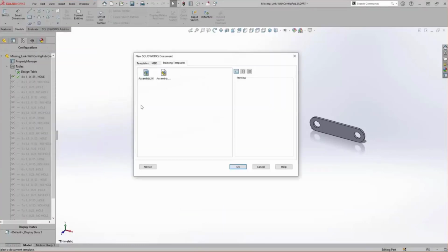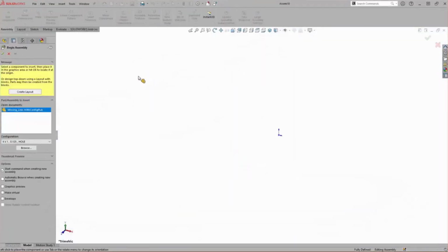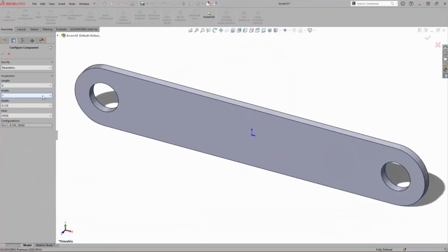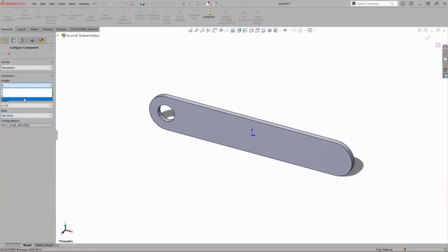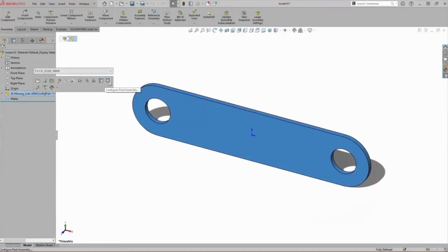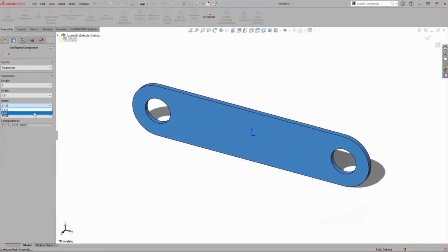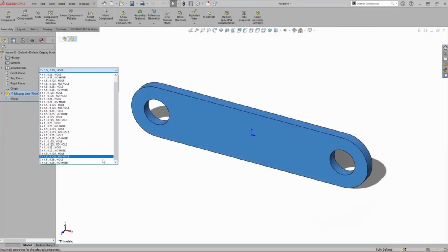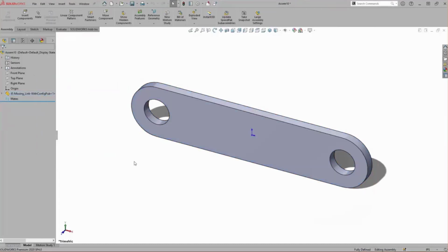So now the final test, let's add this to a test assembly. We'll green checkbox OK. We've got the same type of user interface, but there's no data entry in this example. We're just grabbing information from drop-down lists, different lengths, with and without the hole on the right, different thicknesses, or what I've called the width, or I should rephrase that. The depth is actually the thickness here. But we can get to and redefine that configuration the same way. There's that depth value. So it works similarly. It's a little bit faster because we're not waiting for the software to build it. And from the configuration drop-down list, we can see all those configurations exist, and we could get them that way. So a couple different ways to do that.